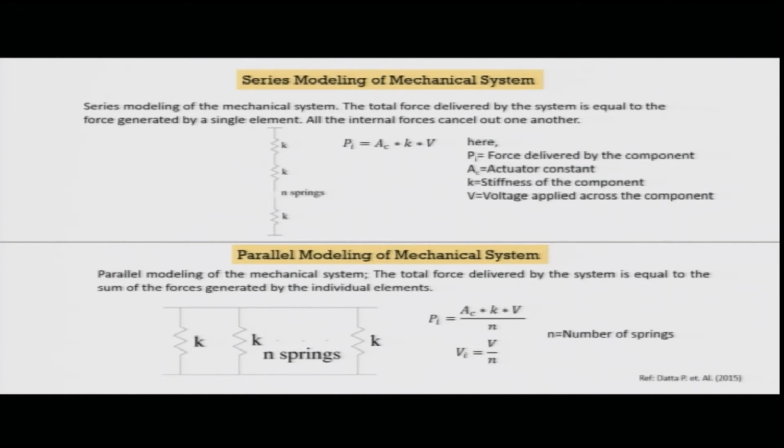First of all, if you stack them in a way in which it is like a spring system, then what is the K equivalent of this system? The K equivalent would actually depend on each K. Let us say each one of them has the same mechanical compliance, I have identically cut them, then for n layers it will be K by n.